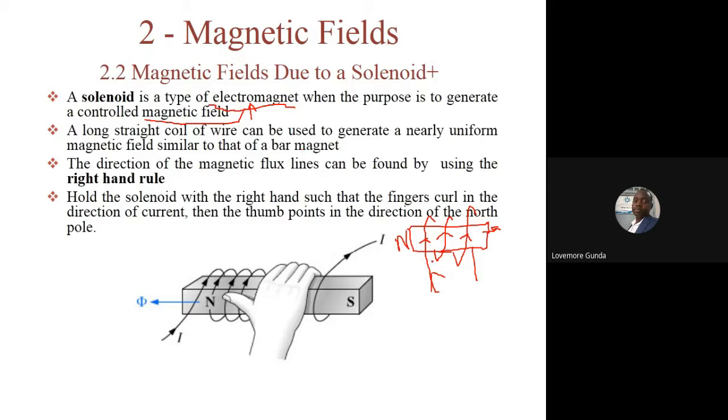So these are some of the components that are used, let's say, in magnetic doors and the like, whereby if you energize, let's say the solenoid is this side, right? Okay, so it should be wound this way, right? Then it gives a north pole and the south pole there. Then on the other side, maybe a permanent magnet with a south and a north pole. So when you energize, then the two magnets will attract each other and they lock the door. When you de-energize, the magnetism disappears and the door is unlocked. So that is where it might be used.